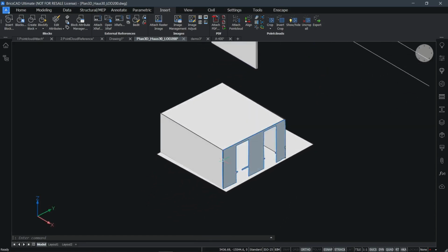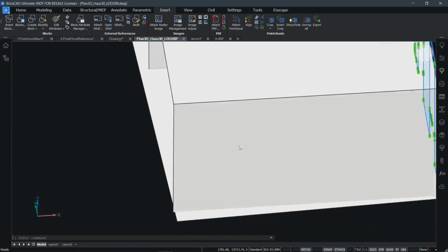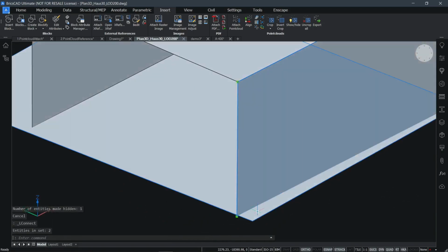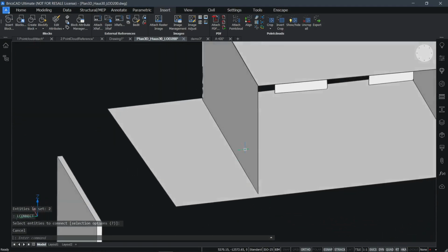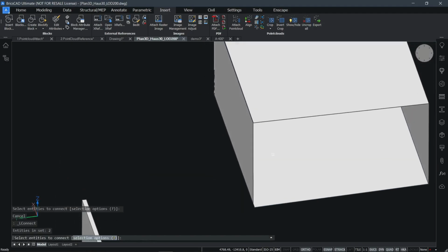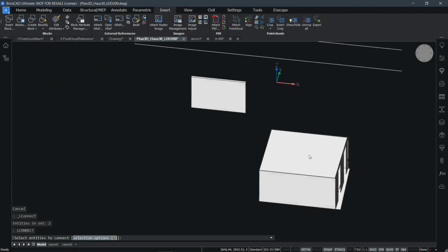Of course, once you've created these, you can, for example, still edit them with, in this case, connect. So these work on planes too, like this. So not only solids you can direct model, but like this you can also use connect for planes to clean up a little bit of the detected geometry.